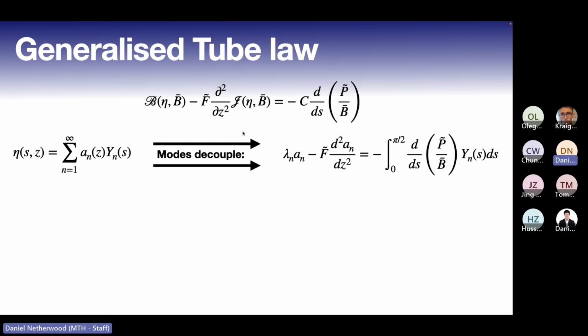Am I right in saying that when you put the fluid mechanics in and couple everything that's going on inside the tube as well, this formulation stays, but you have to be very careful about the P tilde terms? Yeah, exactly. You calculate your hydrodynamic pressure, and then you recognise that P tilde is the difference between that pressure and the external pressure. So you couple via that, and then you've got to deal with all of the fluids. This decoupling is preserved, but when you actually put the fluids in, there aren't adjacent fluid modes that match up with these solid modes. So you do get coupling with the fluid mechanics, but because of some work that we've done, you can show that the coupling is weak, and you can still obtain a series solution for the fluids problem. But it's not quite as elegant as this.